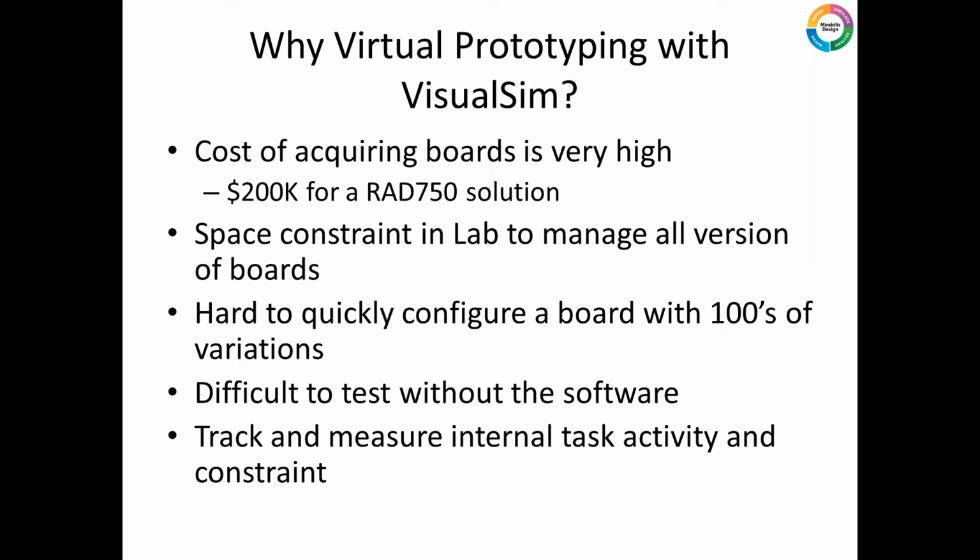The second thing is, a lot of times the software is not available, and having a board without the real software does not make a whole lot of sense. The last one is, the board is really for visualizing what happens end to end. If you want insights into what's happening inside the RAD750 or inside pieces of the board, it's really not set up to provide you those kinds of task activities or buffer activities, or how much MIPS you're getting out of the processor, things like that. Especially in technologies like the RAD750, where you only have about 200 megahertz and you have a considerable amount of software that needs to be loaded, you need to get maximum capacity utilization.